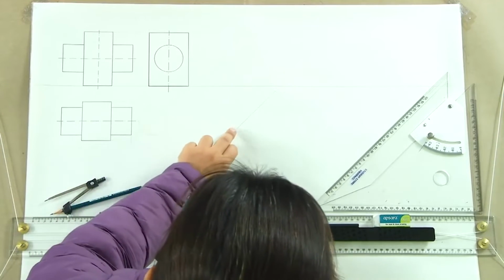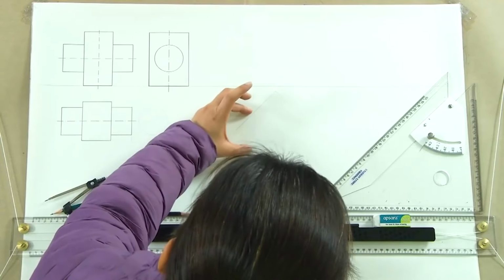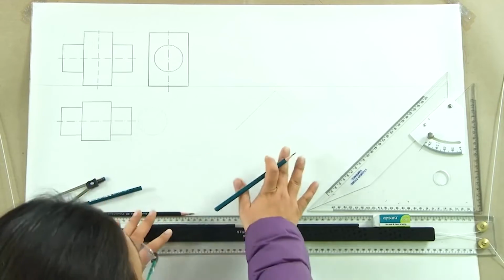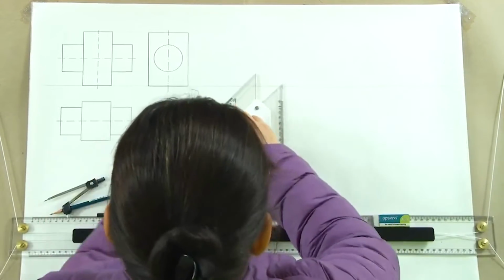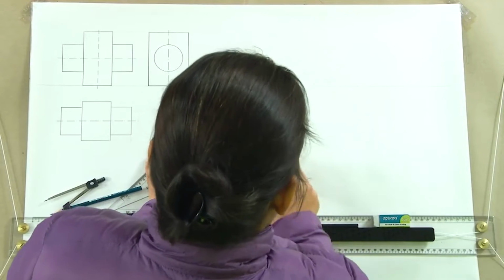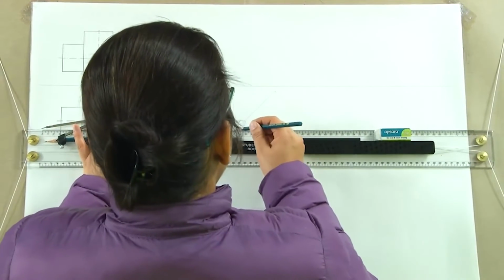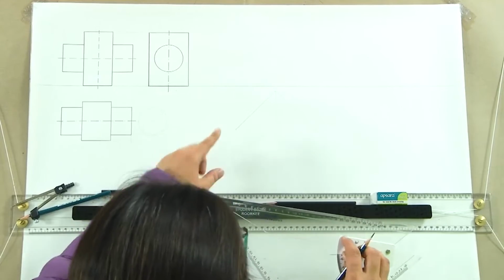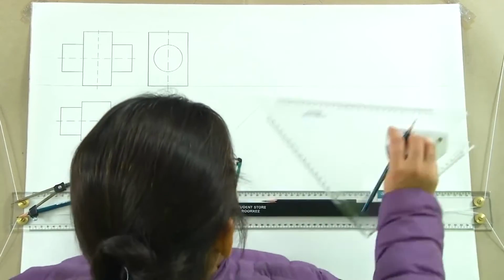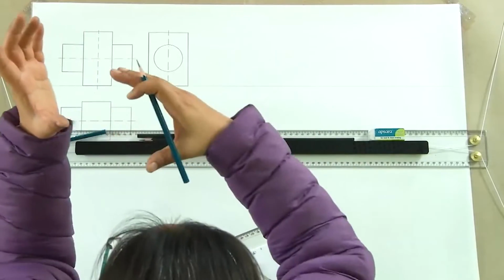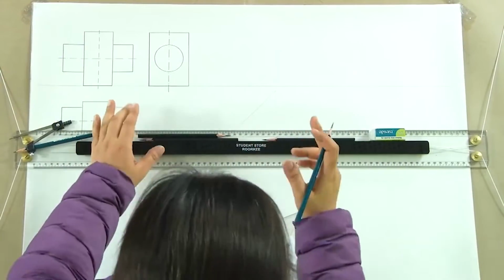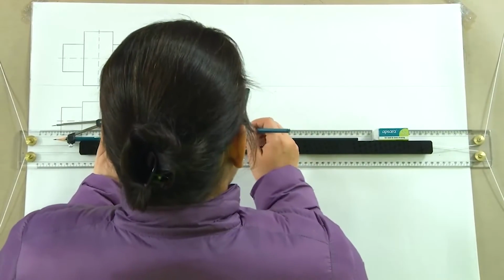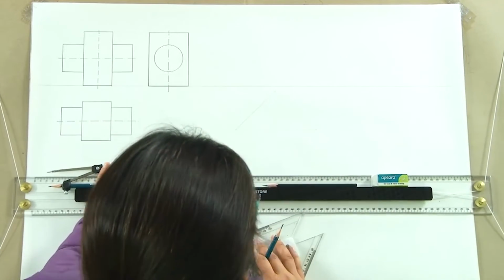Now, it says that the cylinder enters one of the corners. So, it enters diagonally, it exits diagonally. How long, we are not sure as of now. The only thing that we know is that the axis of the square prism passes through this point, and the axis of the cylinder which is intersecting will appear. So, it is actually parallel to the VP, but it is inclined to HP. So, since it is parallel to VP, we will be seeing a straight line for the axis here, which is what it is.